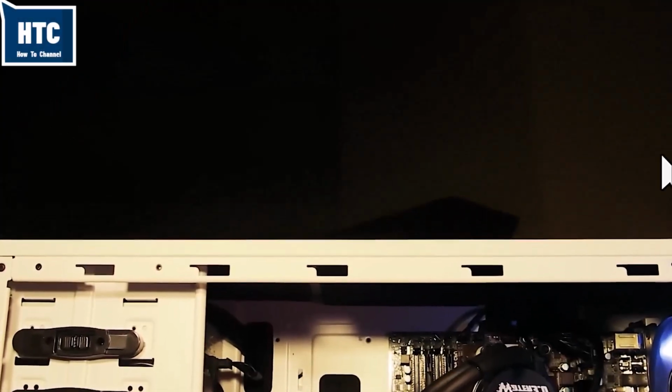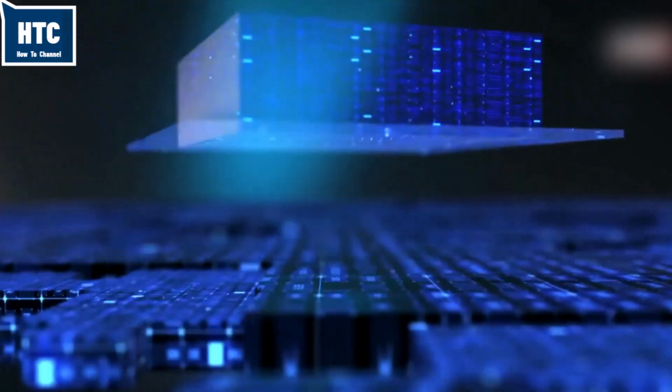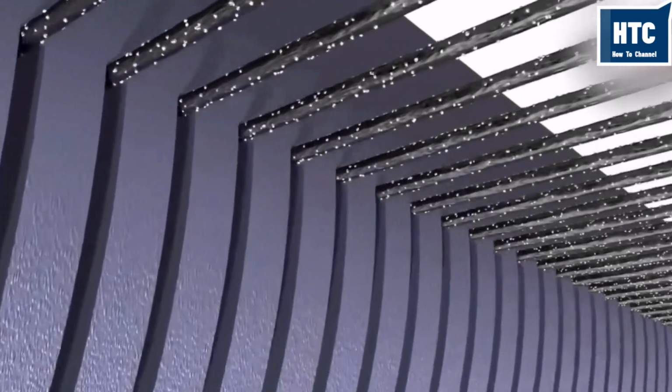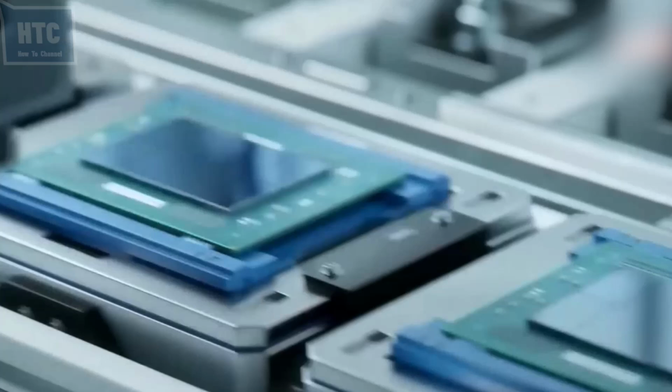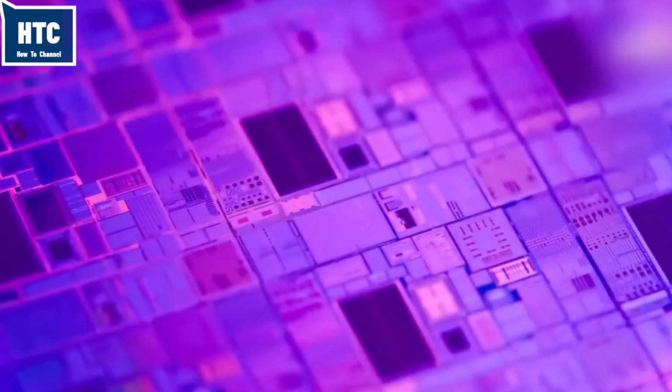It begins not with matter, but with logic. Before a single grain of sand is mined, a CPU exists as code. It starts with the instruction set architecture, the language the computer speaks. Engineers write register transfer level code, simulating how billions of logic gates will interact. This blueprint is virtually tested for months before being finalized into a physical layout known as the mask set.